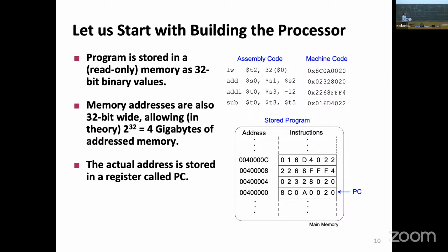Now, the first thing to realize, or the easiest one to realize, is the following. Am I going to write back something to the register file? Store word, who says no? In the store word, we are not writing anything back to the register file. So we are not going to write anything. Therefore, it doesn't really matter what I have for the register destination. I'm not writing anyway. Who cares where I get this address from? Does that make sense? Also this side? This side is good?